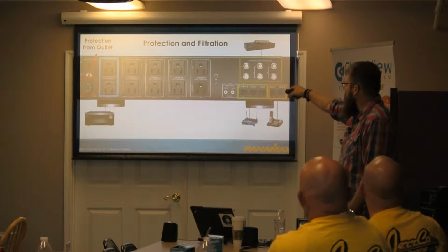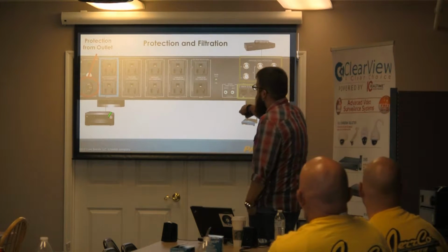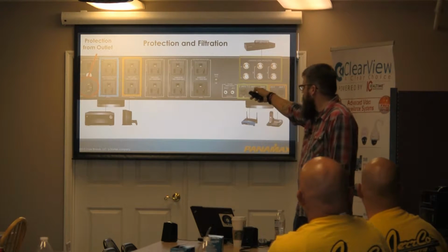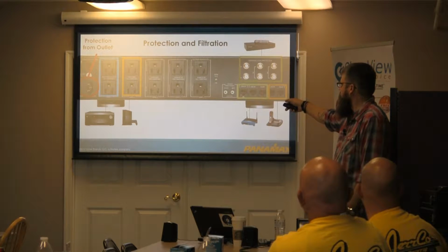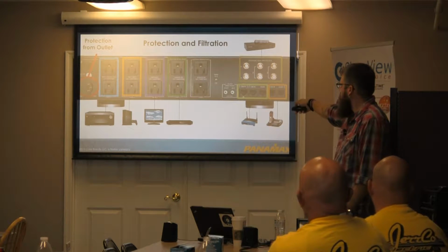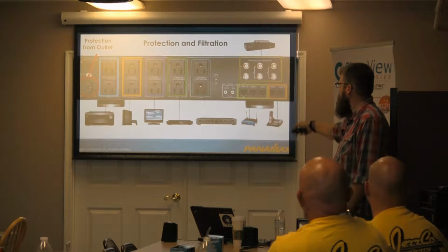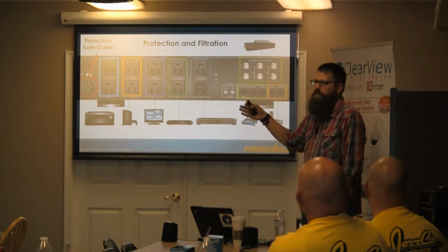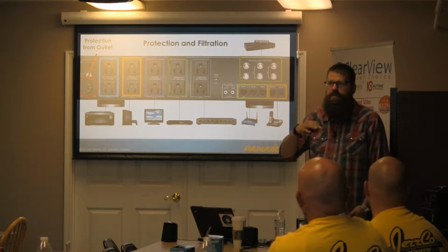High current. The first bank here is our high current devices, so we've got our AVR and amplifiers plugged in here. Gaming or any other device, Apple TV, what have you, in the second one. Panel power going to another one. Source component to there, and then audio to there. Each one of these banks is isolated, so there's going to be no crosstalk between the two.